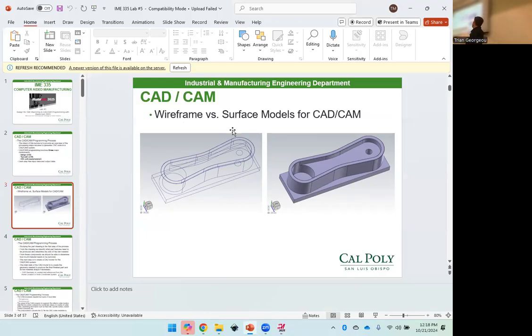But with technology, we can bring in our SolidWorks model now, right? And program directly off of our model. And I'm going to show you how to do both, because there's times you need to use wireframe geometry or extract wireframe geometry from your model to make a toolpath work right, or to maybe constrain a toolpath, or to go ahead and drive a toolpath. Sound good? So realize we can use wireframe and surface models for CAD/CAM.